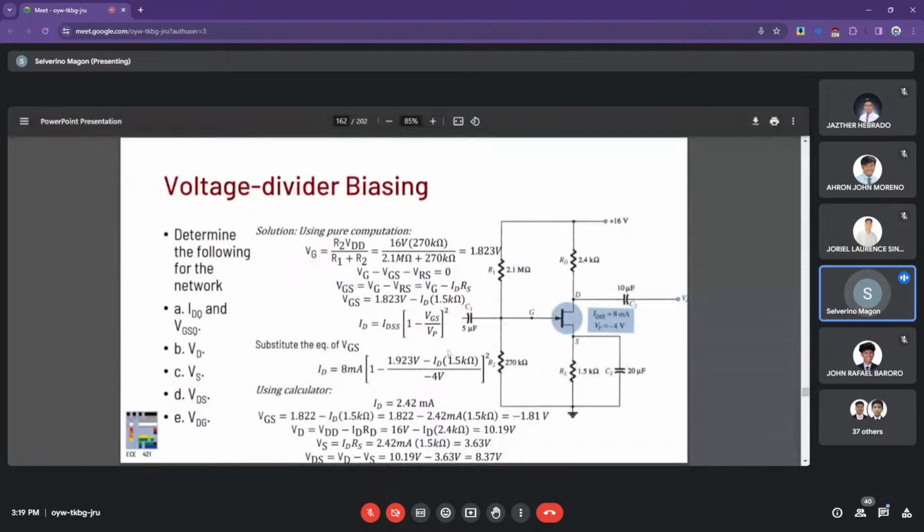But when an AC signal comes in, well, more on the analysis in the next session. But again, when the AC signal comes in, an amplified AC component will be superimposed on that 10 volts. So a larger version of the AC will be riding on top of the 10 volts output here. And that larger AC component can now pass through the capacitor because the capacitor acts as a bypass for AC signals.